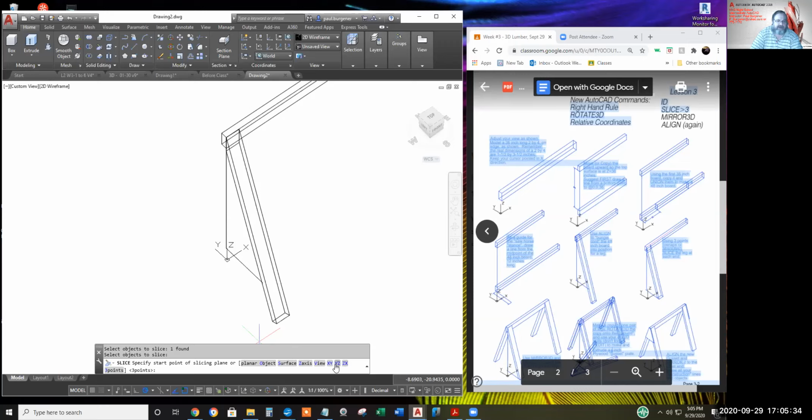Well, let's try the XY and see if that's a shortcut to slice it off at the floor. You with me? Yes, that looks like it would work perfectly. Again, I always use a 3 point, and you just pick points out here in random space, being careful you don't follow any of the polar tracking lines, especially the Z direction polar tracking line. But 3 points out here in space will define 3 points on the Z equals 0 or the XY plane.